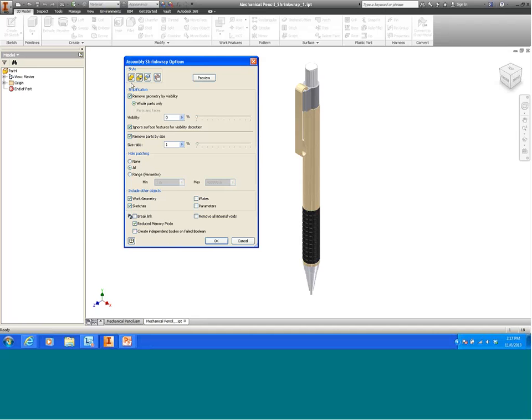This is only available when you're creating single body, so these first two style options. It's only available here so that if there was a failure during creation of the shrink-wrap model, because maybe two features or two parts in your assembly aren't actually touching, it would then instead flip it over to create a multi-body part automatically without a failure occurring. So this is a nice time saver.